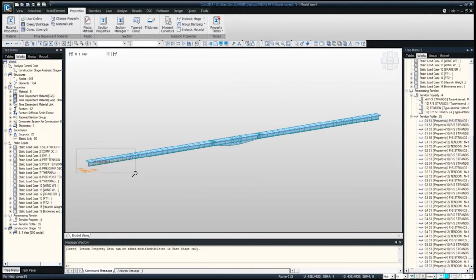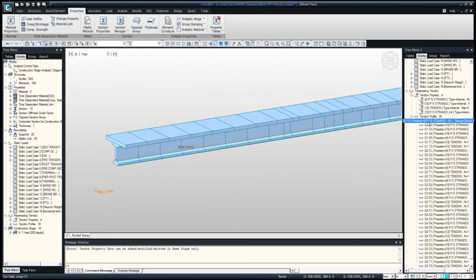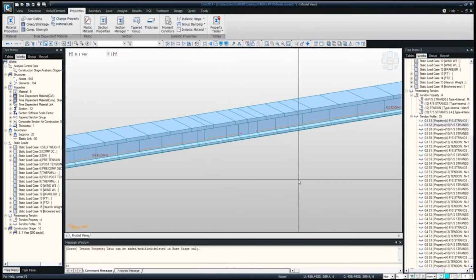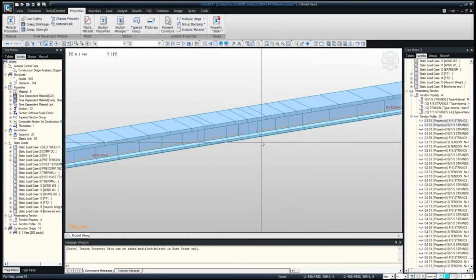Okay, so here we have the post-tensioning strand in the first girder segment. Turn on 1 and 2 so we can see how that does not go through the splice. And there we go. We have bottom pre-stressing in the pre-stressing bed that does not transfer through the splice.